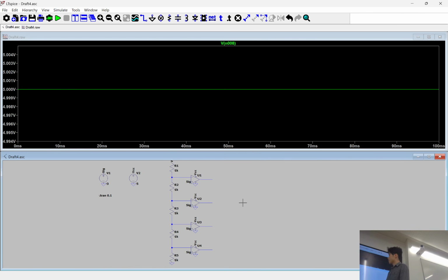In terms of the possible configurations, if we have a very large signal, it'll all be ones. A little lower, these 3 will be 1, this will be 0. A little lower, these 2 will be 1, these 2 will be 0. And a little lower, this will be 1, these 3 will be 0. So we've got those different possible values. And I want to sort of map those to my 2-bit binary number.